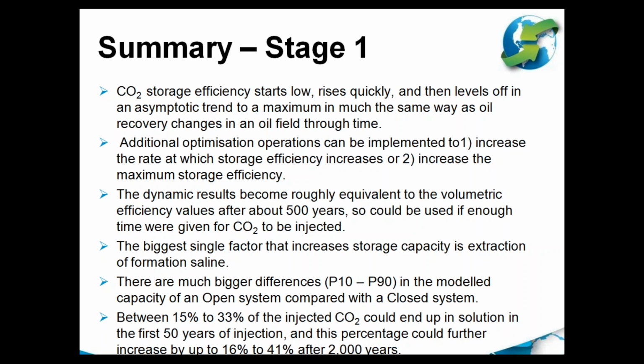The biggest single factor, as might be expected, is the extraction of saline. There's a much bigger difference between the P10 and P90 in an open system as compared with a closed system, which reflects the geological and reservoir suitability of formations such as the Minnelusa.